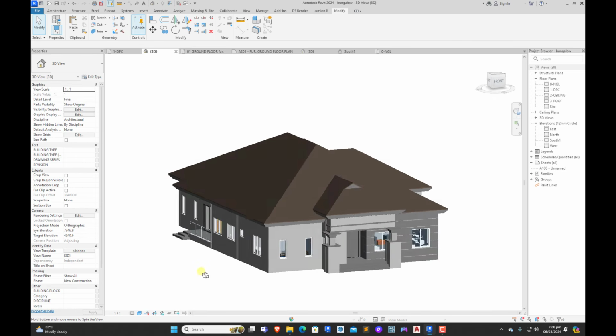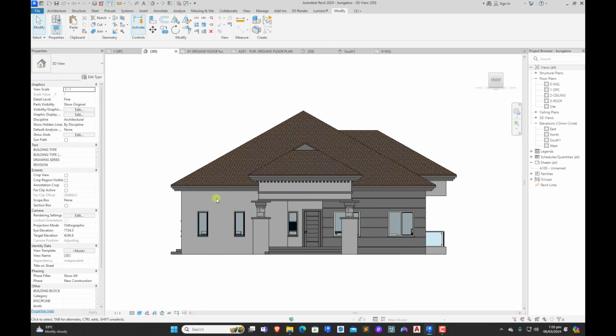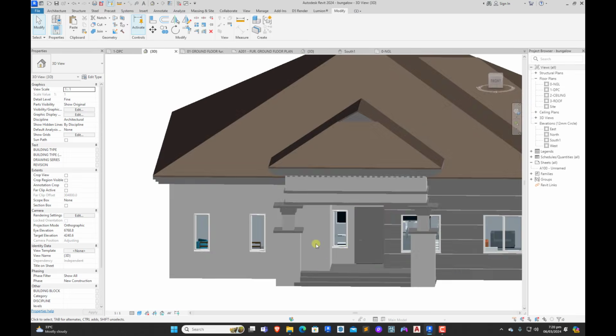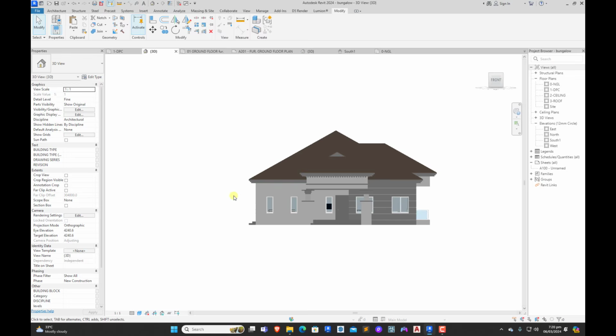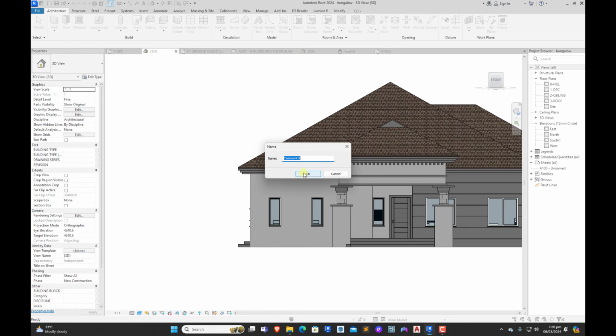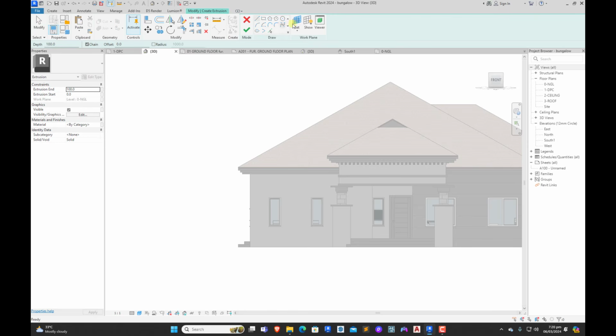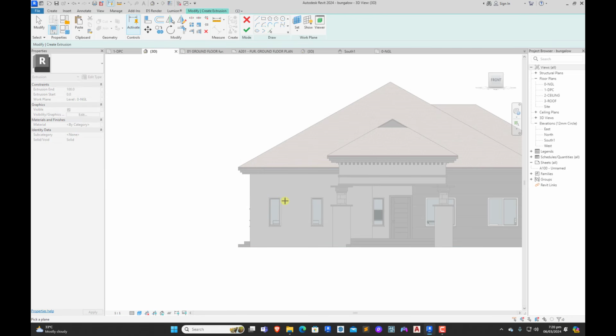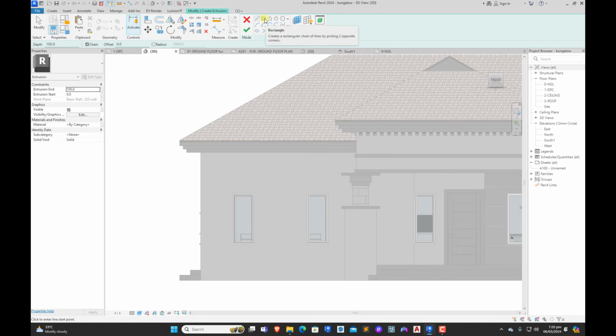Next thing we need to do is to add some extrusion to this point. Alright, so we're going to click on this component, model in place, casework. Okay, we click on extrusion, we set the plane, pick this plane, we pick this wall. Good. Then we can now draw our extrusion. Let's say we want it this way, down to this point. Okay.